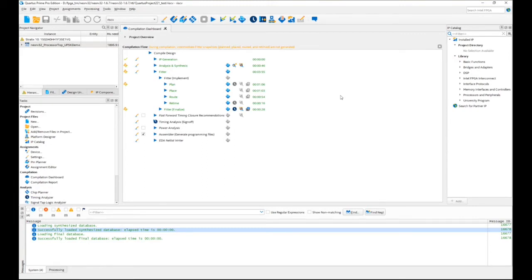I'm going to start with the newest, Agilex and Stratix 10. Those are what we call our Hyperflex architecture, because the architecture adds more to what a traditional FPGA architecture deals with. When I say traditional, I'm talking basically a register lookup table combination. Stratix and Agilex have a register lookup table combination, but in addition to that, they have registers all over the place inside the routing infrastructure. And so that's why it's called Hyperflex.